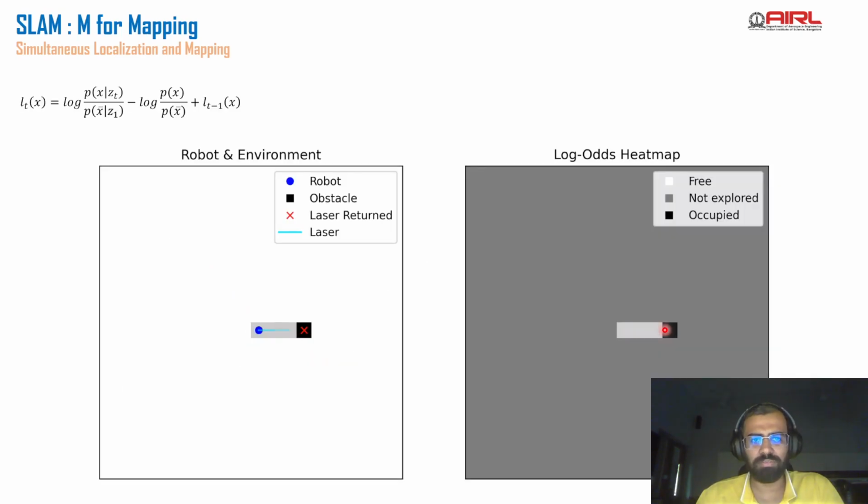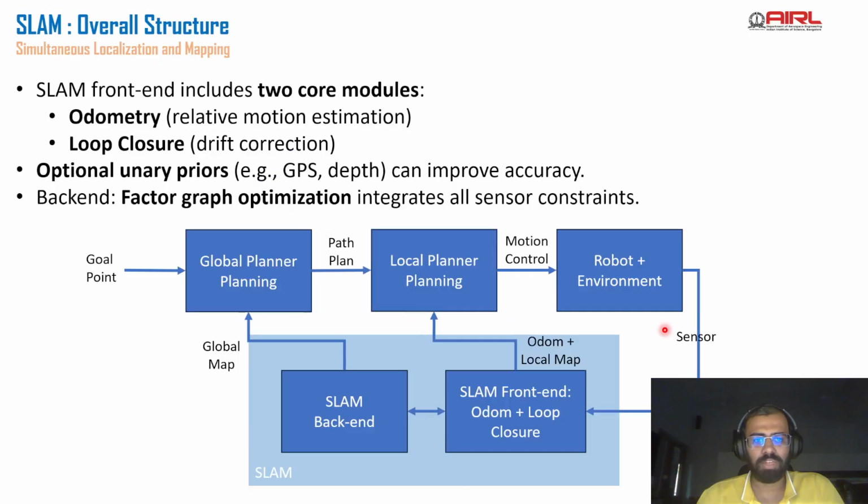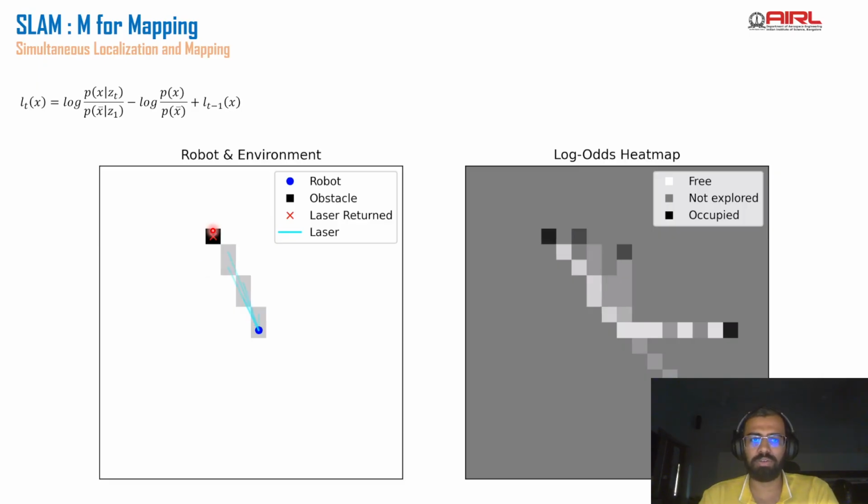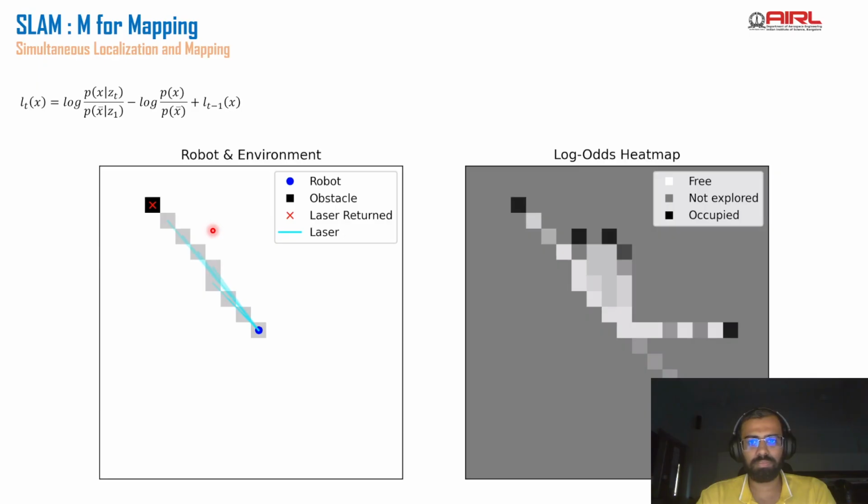So let me replay this again, and make sure you check the observation, the laser observation you see on the top left as well. There also we see an erroneous reading and then we see a good reading. Yeah, we see that the cell was occupied and then it became white. I would not really say it's erroneous, it's just that maybe the environment changed or something else happened, right? So that's the gist of this whole mapping part of our 2D SLAM map.